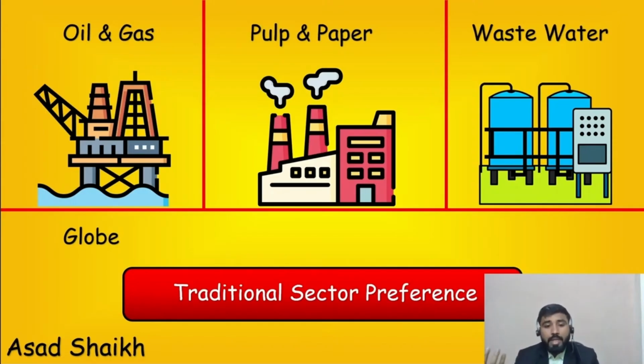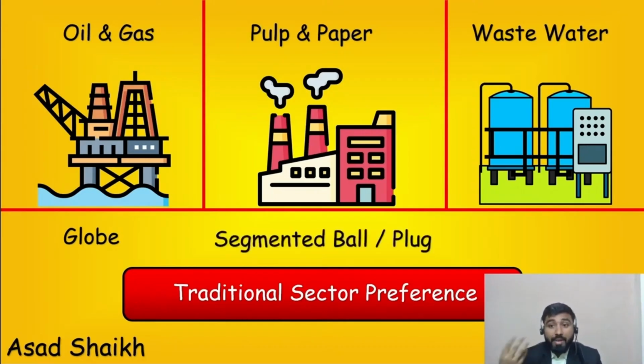When it comes to pulp and paper, it is not extremely challenging, but not as easy as just water treatment plants. So generally they have a preference for segmented ball or plug valve design. And finally, when it gets to wastewater, most of you answered that because those are not challenging applications, you might first try to go for a butterfly valve.